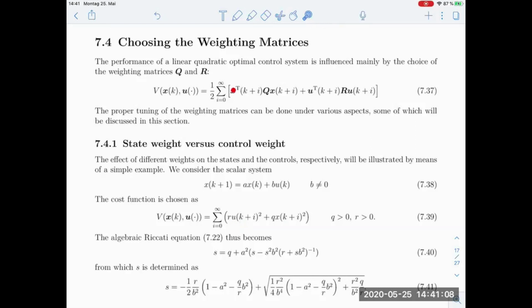As you see, this vector notation is not necessary now. And that's actually why we take this approach, because we can reduce all the Riccati equation to a simpler quadratic equation then. Let's see how we do that. So particularly, we'll choose Q and R positive, but we will look at various ratios of these, very small and very large, to look at the boundary cases, what happens in the system in these cases. So the algebraic Riccati equation will become of this form here. This form is still too complicated for a simple solution here.